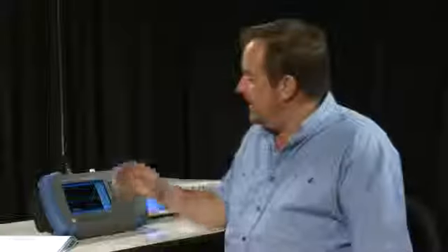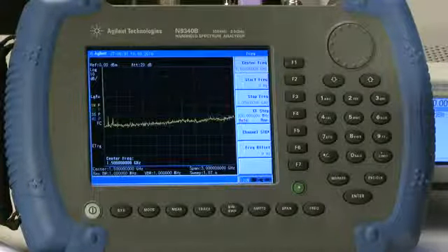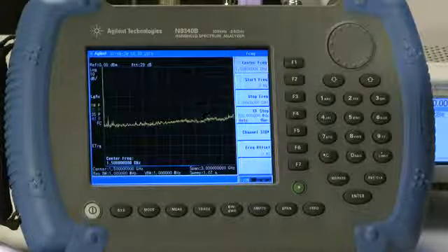With the RF spectrum becoming ever more crowded, the ability to see transmitters turning on and off over time is a very useful function, both for interference analysis at base stations and for surveillance by the military and security forces. Turn to section 8 in the demo guide and you'll see how we can use the spectrogram capability of the N9340B to identify and measure signals across a wide spectrum over a period of time.